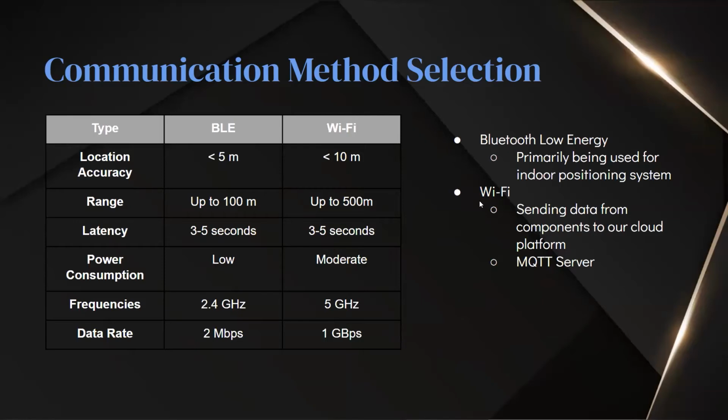For our communication method selection, we went with BLE, like described in the previous slide. With that, we'll be able to use our indoor positioning system, and it'll be more accurate with BLE compared to other methodologies based off of the latency, its range, and its power consumption.